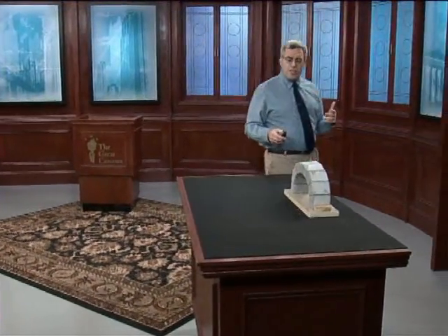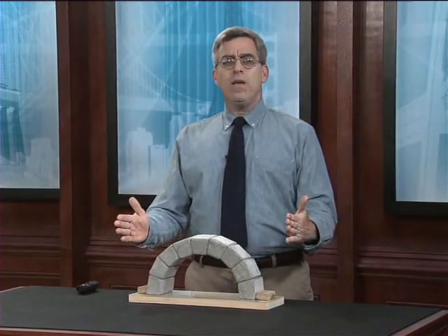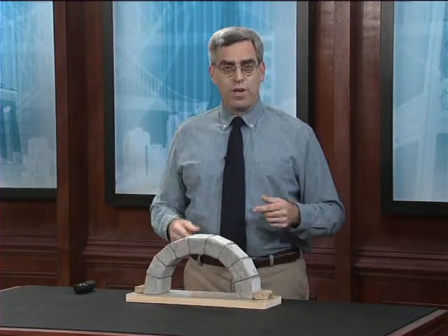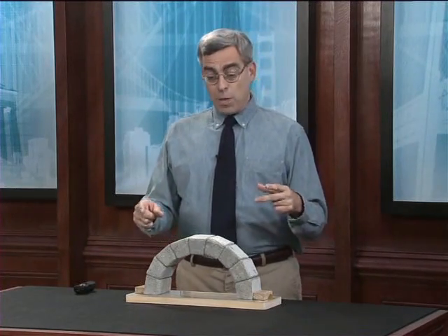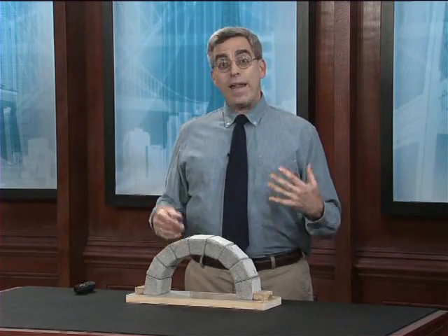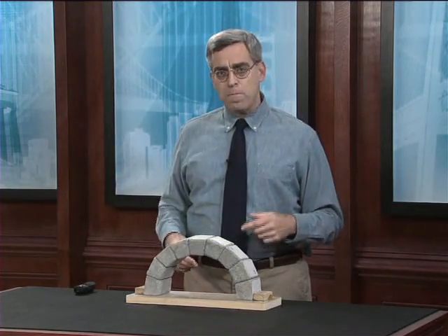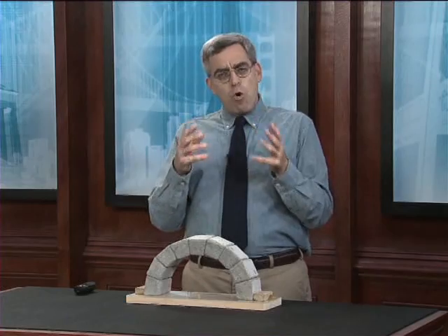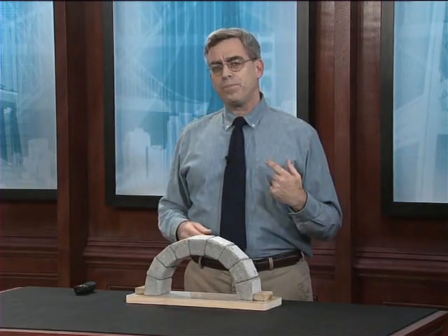But the principal structural characteristic of an arch is that it carries load entirely in compression. So as a result, the span isn't limited by the low tensile strength of the material, or by the sizes of the individual stones that make up the element. It can be built up of many, many smaller stones or bricks, like my model here, and as a result, greater spans are possible than could even be conceived of with stone beams. As a result, the Romans' use of the arch opened up a whole new realm of structural possibility.